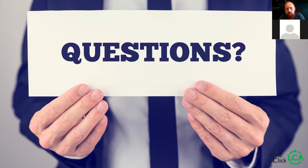Then Anna asked a question about what type of LCA should be done for comparison of, basically, different end of life methods. The materials we have in our database will have different end of life methods available to them. So if you have, let's say, a quantity of 100 cubic meters of wood, you could do one which follows incineration as the end of life method. You could do one which follows landfilling. And if there are some other options, you could probably compare those as well. It's possible.